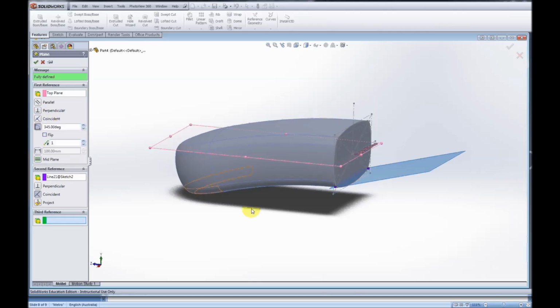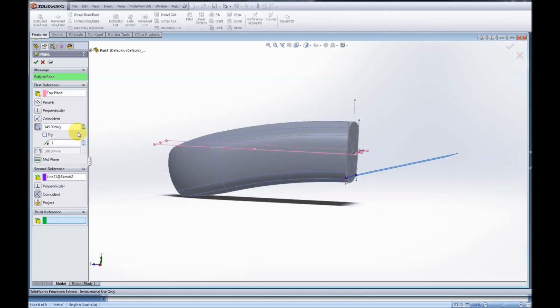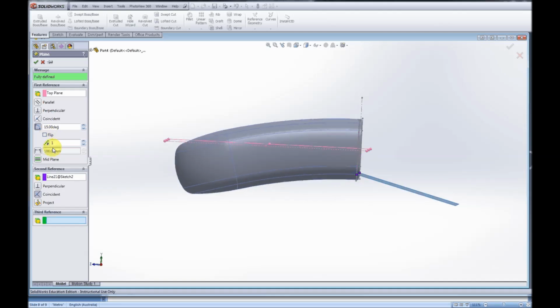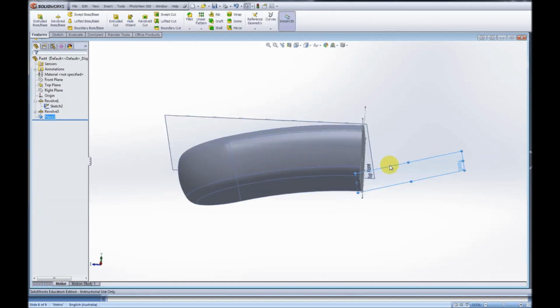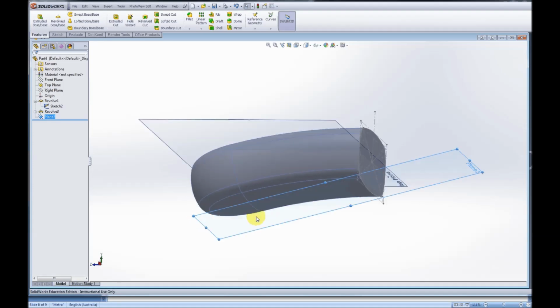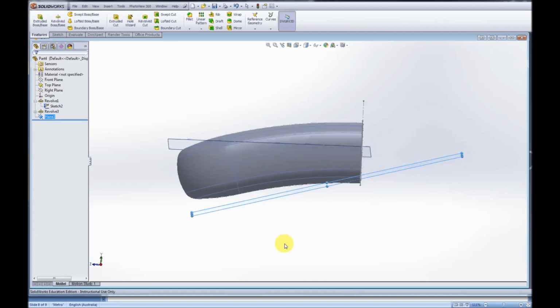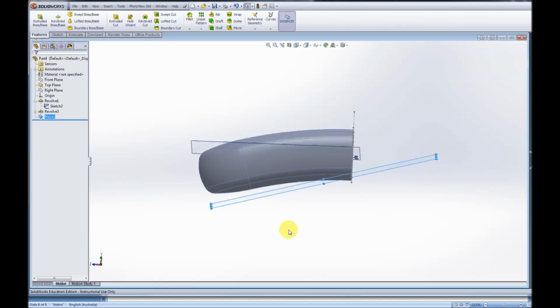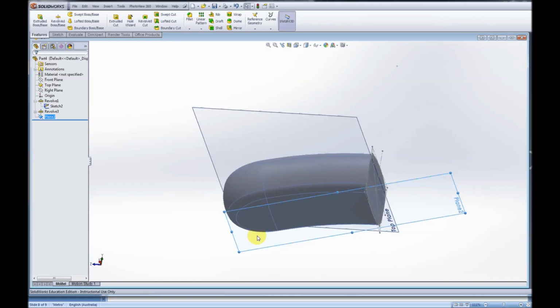all we have to do is tell it we want to create an angle. Now, because the revolve was through 15 degrees, this plane also wants to be 15 degrees. Now you might find that it's looking like that, which is the wrong angle. We actually want to have it at this angle. So hit OK. Now we have a plane which I'll just drag to make it a little bit larger, because we're actually going to be drawing on this end of the plane, and that's at the right angle to where we want the loudspeaker to be.